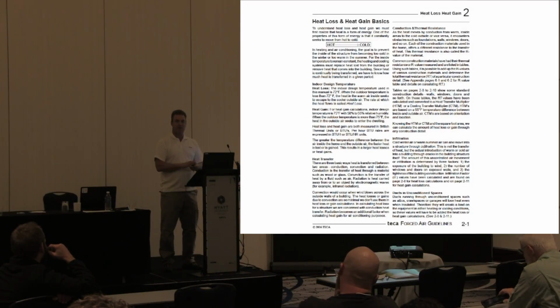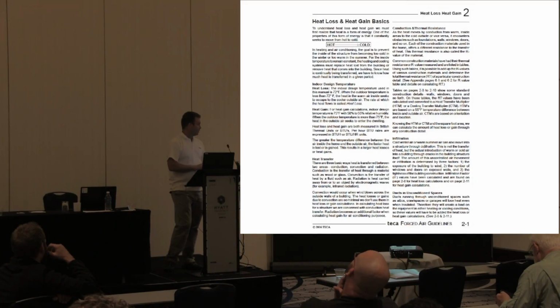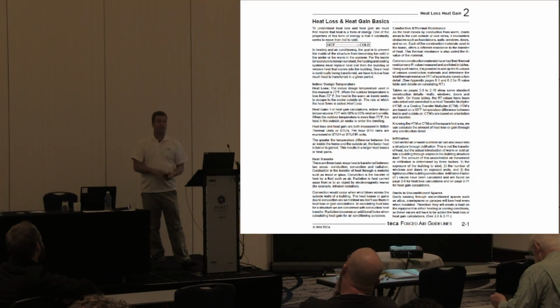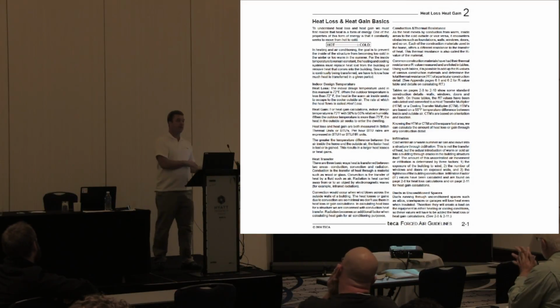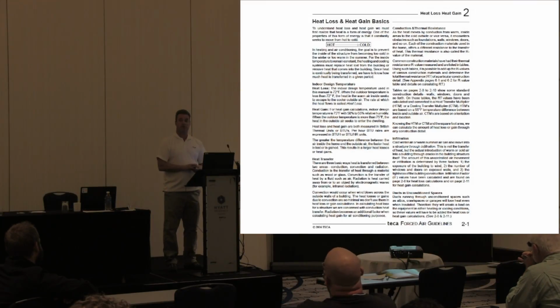So make sure you're covering the standard, which is 72 degrees, and then 75 for the air conditioning side is what TECA teaches to size to. Other guys will do other heat losses that may use a different number, but you need to know what that number is. If they're only tempering their air to 75 or 78, and you know that customer is going to want their house at 69 degrees and they have lots of windows, it's not going to be the same size as their neighbor who you just put in that's going to keep it 5 degrees warmer. They're going to want a bigger unit in that house.